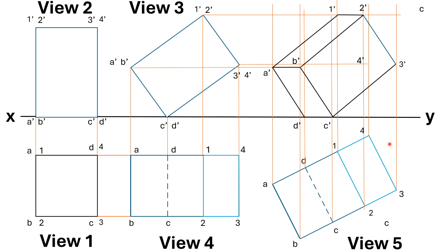If you take the outside lines, here A dash 1 dash is actually above this imaginary line, but because it is an outside line, I will make it a dark line, because outside no hidden line will be visible. And 1 to 2, half of the line is above this imaginary line and half of the line is below the imaginary line, but still it is outside the boundary, so I will make it dark.